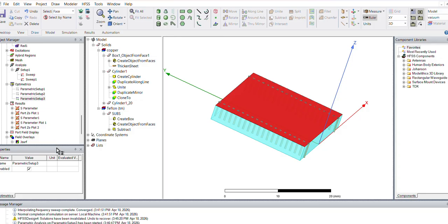So we did the parametric sweep, and what should we expect? When we are increasing the distances between the PTHs, the energy should start leaking out, and we should be able to see that. That's the next step. One more thing we shall do: we shall put an outward boundary, an outward waveguide boundary encasing the full waveguide, and there we shall be able to see what is happening.